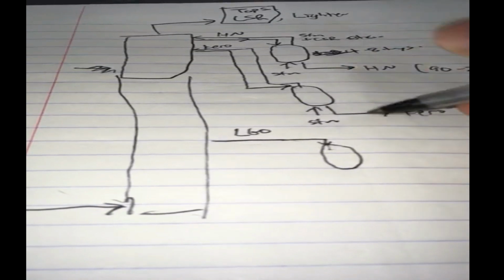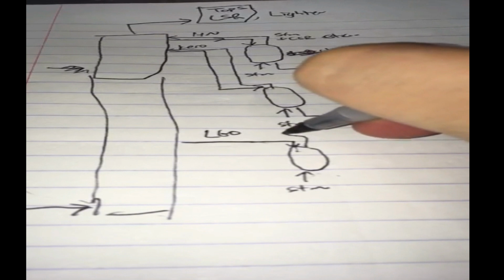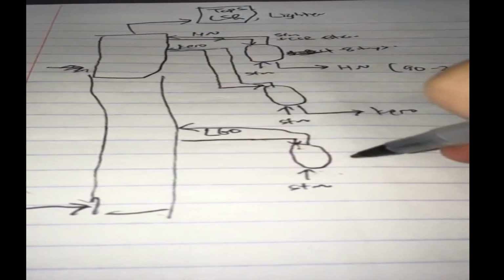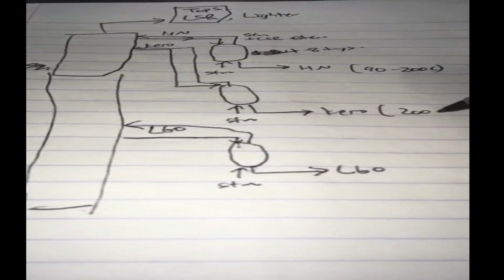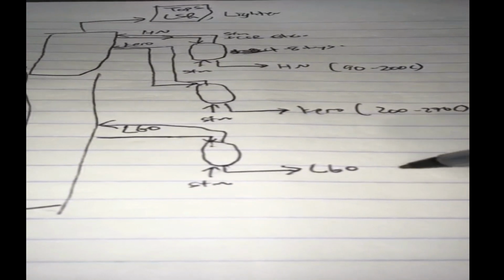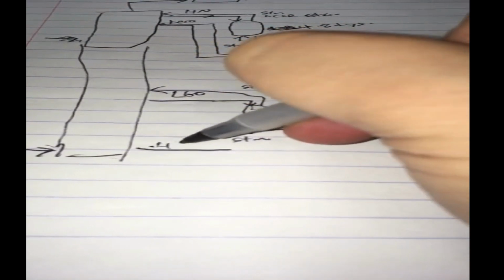Light gas oil, steam, and back. This kerosene is 200 to 270. Light gas oil, 270 to 320. And you have heavy or atmospheric gas oil.